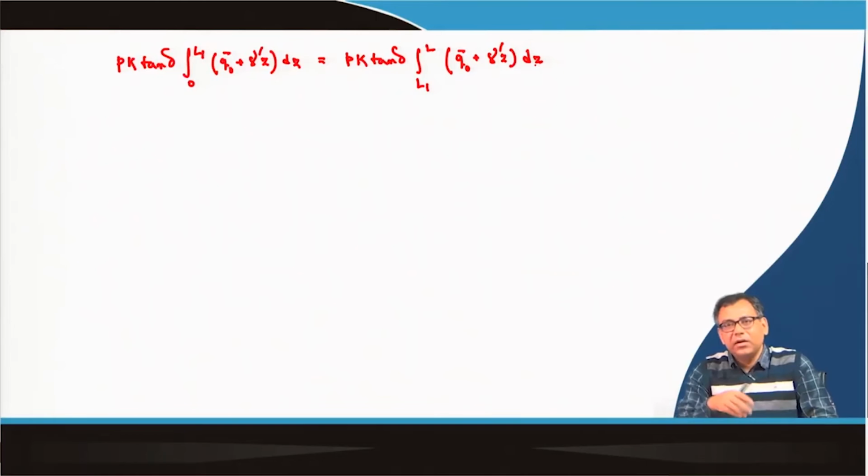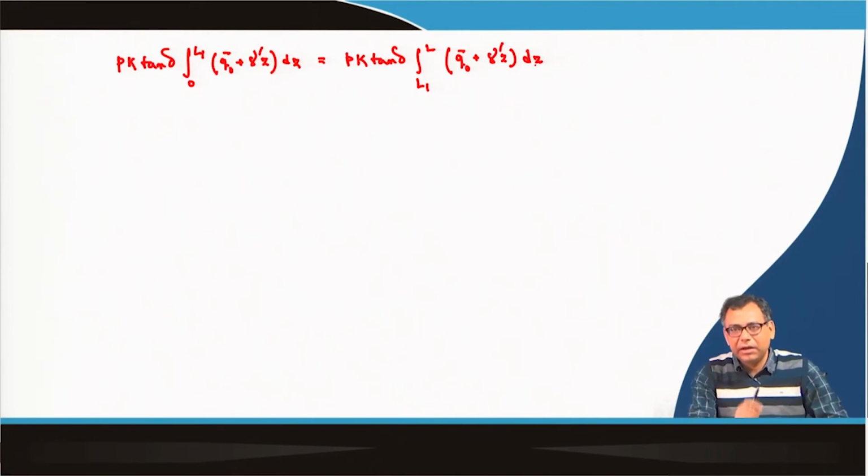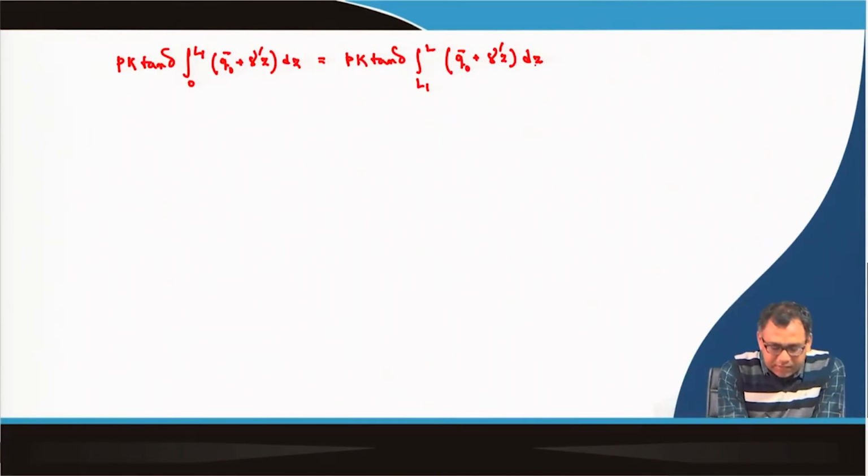So, that means we have to make the pile length sufficiently large, so that the developed negative skin friction can be counterbalanced by the positive skin friction. So, if I cancel this both sides, then we can integrate this. So, this will be Q0 bar into z, if I put limit L1, plus gamma dash into L1 square by 2, because it will be z square by 2.